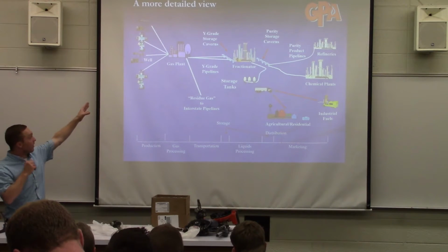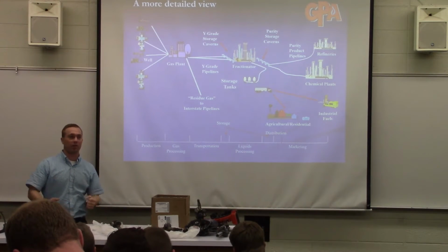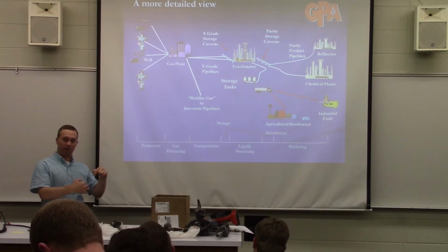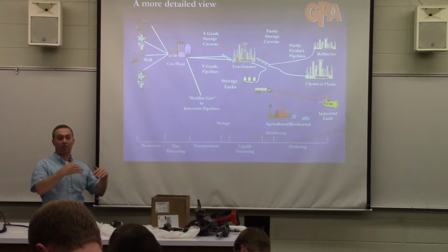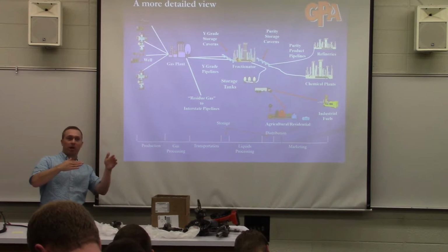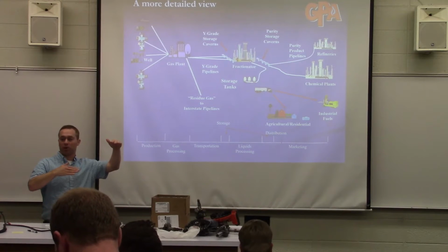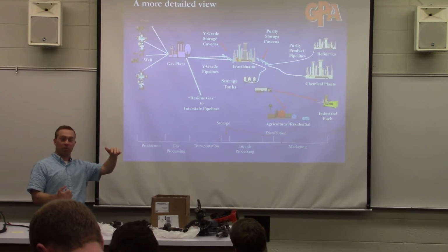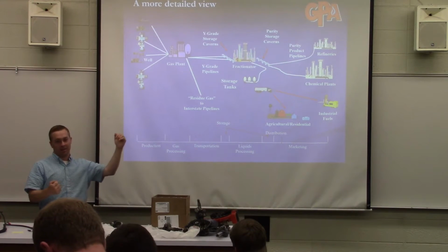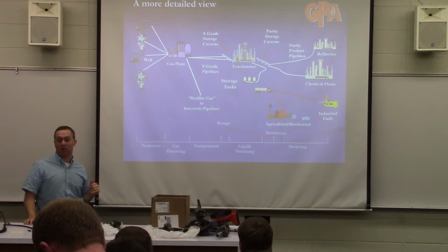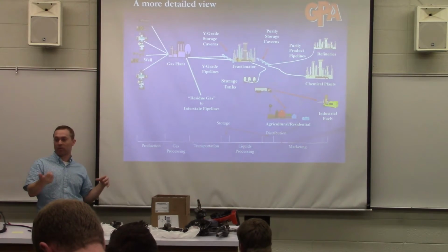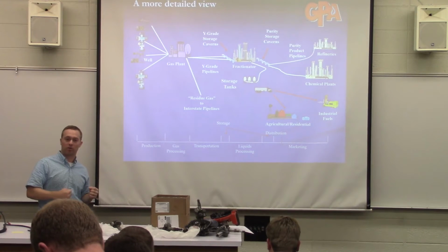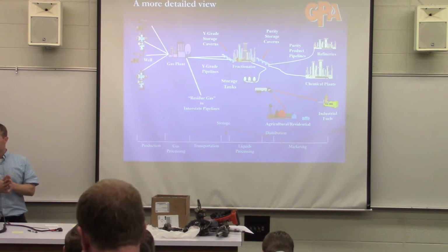So in our gathering systems, producers like us to suck the pressure down low because they get higher production, right? If the field pressure is at 1,000 pounds, then the developed back pressure, their wellhead pressure might be 1,400 pounds. Versus if we suck that down and that field pressure is 100 pounds, they're going to be able to flow more natural gas. So that's a reason why we'll have field compression to suck those pressures down for them.